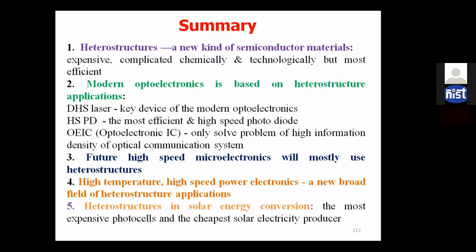commercially there are 14 nanometer and 7 nanometer node length CMOS, but when we reduce the node length, we should think of alternate materials, where the heterostructure, particularly the III-V heterostructure, will be the prominent material, because III-V heterostructures have higher mobility and higher transport properties.